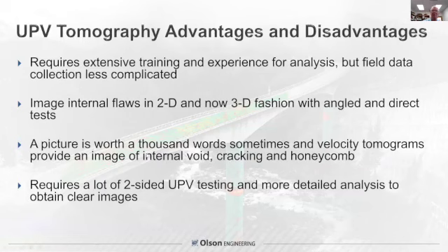So a picture is worth 1,000 words. Giving people an image, we've done this on dams, on underwater testing of drilled shaft foundations with processes like logging, on geotomography in the soil and rock. But tomography is used for a variety of things, similar to the CAT scan that everybody's heard of, except that's amplitude of radiation tomography. And now we're talking about speed of the stress waves, sound wave tomography, for a velocity tomogram in this case. You do need more testing and more detailed analysis to get an image.